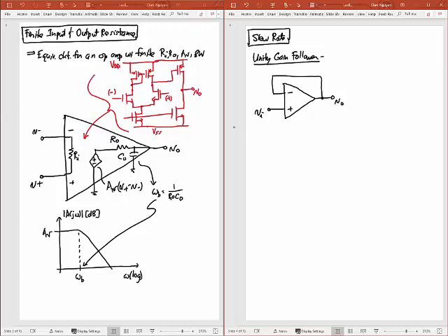Exactly, yeah, so it's a more ideal driver circuit. So if I had a load out here, if this were ideal, then the op-amp would have zero output resistance. If it were a real op-amp with finite output resistance and was designed well, then that finite output resistance R0 would be a small value, and it would still be able to drive a finite load, like 1 kilo ohm or something like that, or even 50 ohms or so. Okay? But anyway, this is our unity gain follower.